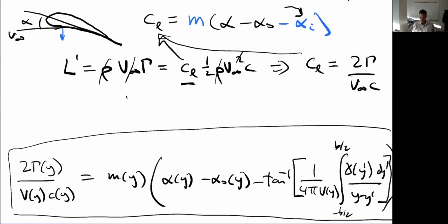I could solve for a gamma, and this is the derivative gamma. So those are really my only unknowns, is trying to figure out what that circulation distribution is. I'm figuring out what the lift distribution on the wing is from the geometry. Though, it's potentially difficult to solve. I've got an integral, I've got derivatives and so on, and arctangents.